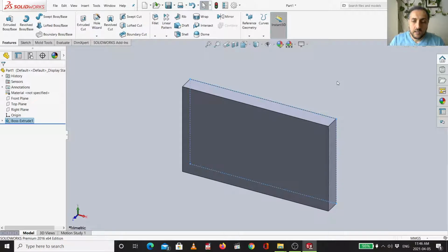Okay. Now, our model has a round circular hole here in this place. So what is the best plane to choose? Actually, not those, because those are on the back side. So we can choose another new plane, which is this one.